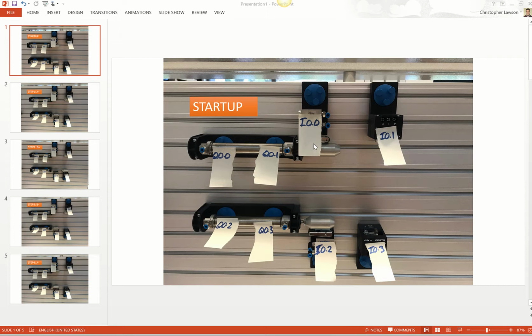We're not going to go into the full solution, but we're going to build it up until the key point where we need to add in some memory or a marker, and how we can use that. You'll see some tags here, which is just the setup we've got. Don't pay too much attention to the types of inputs and outputs. Just assume that we've got an electrical roller switch at the end for each cylinder to sense its extended and retracted position, and then I can turn on a solenoid to either side of the double acting cylinder to either extend or retract the cylinder.